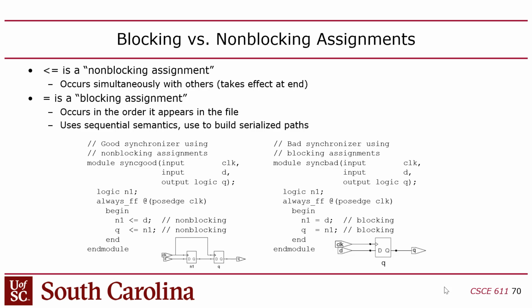So in your control unit in your CPU, use equals, but in your flip-flops, in your register file, and any kind of memory, you use the less than equals. You guys with me? Okay.